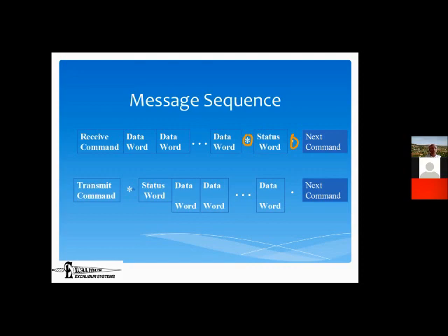And in fact, good practice is when you develop a new bus, you don't really want to use more than 50% of the time available to you, because in another month, somebody's going to come up with another message that he'd like. And if you filled it up to start with, you've got no room to grow. So you're really best off not filling it more than halfway. And then you've got space over the course of potentially years before you actually fill up the slots. Now, if you do fill up, then you're up close to 100% throughput. So then you've got a problem. If somebody wants to add something, what do you do?